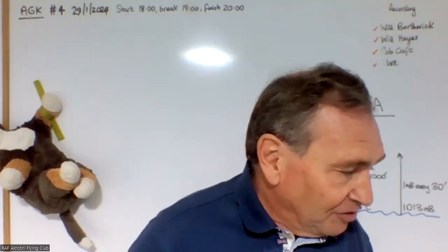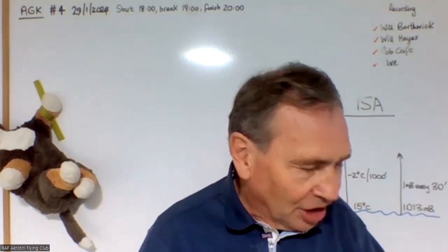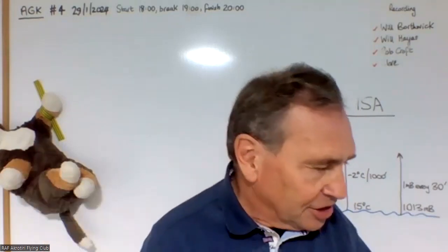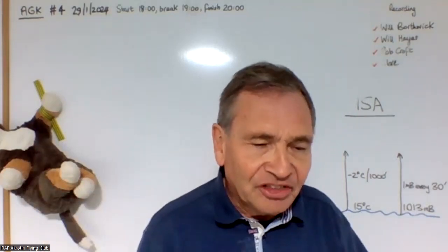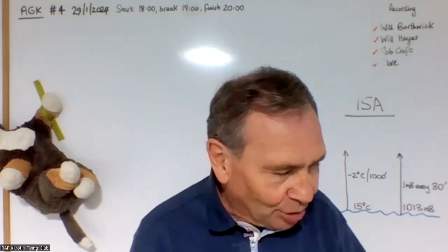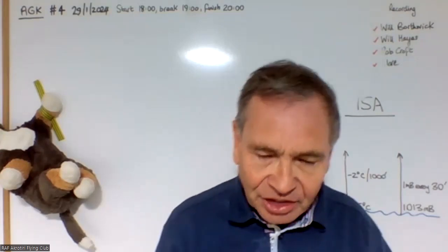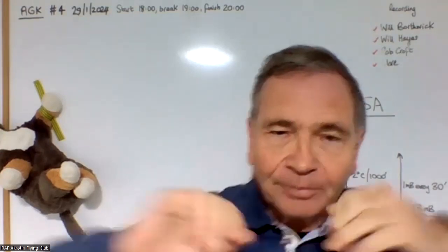And that way, even if the electrical system fails, or it's all fused and the circuit breakers have all popped, you've still got a little pump that's bolted to the engine that's making compressed air. So let's have a look at a typical diagram of this compressed air system.